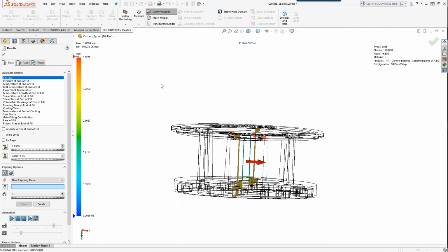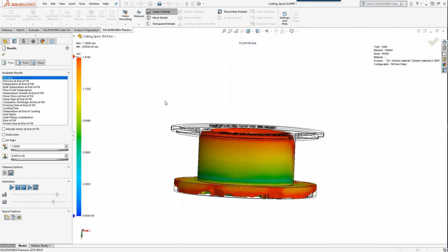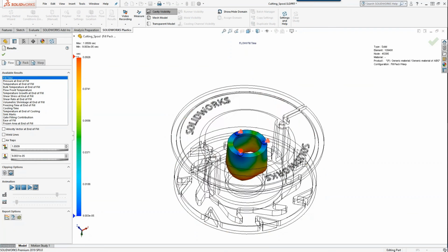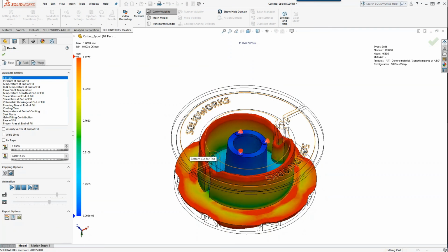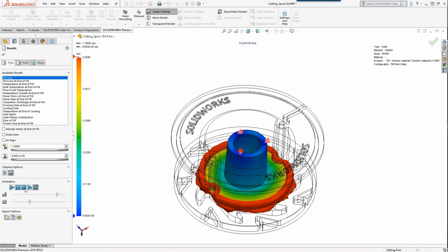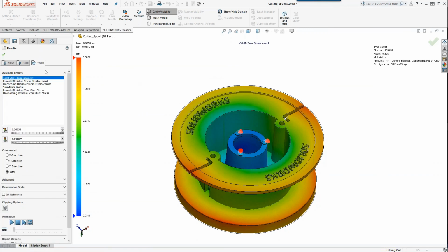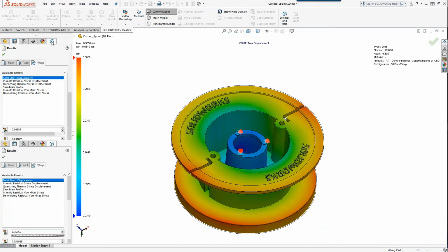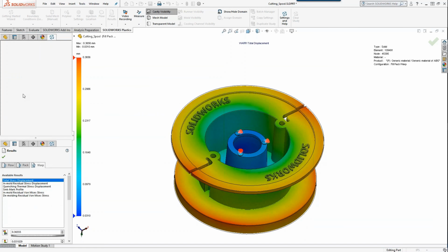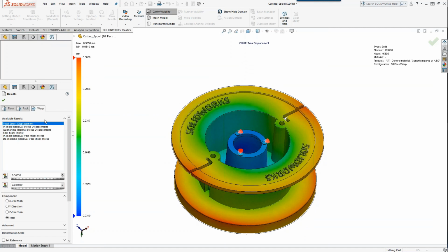So of course, like I mentioned, the part does fill up without any issues, but just so you can see how it fills, evenly. And I think what we are most interested in here is the warp analysis. So based on just the two parameters that you had set, which is, I'm just going to go ahead and hide that, the ambient temperature and the ejection direction, we can get quite a bit of results.